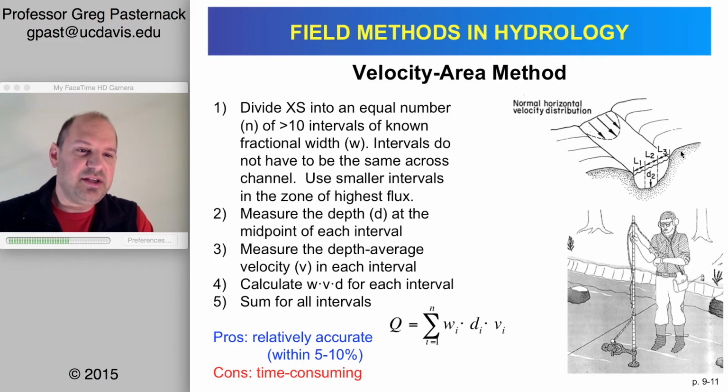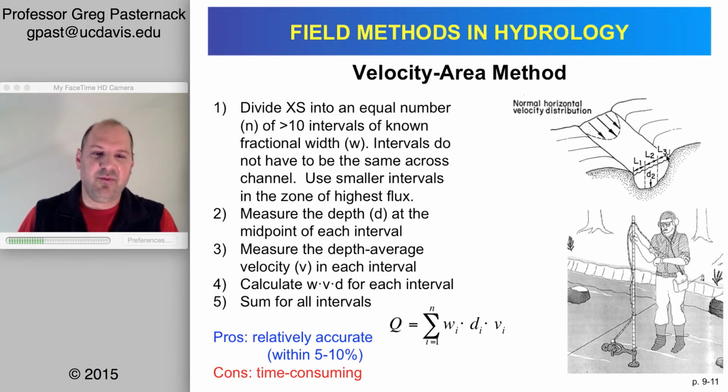The last thing I want to tell you is that for the left and right bank, we're usually not going to treat that as a square, because you can see how much of the square is cut off. This is a very small channel. Both L1 and L3 are fairly truncated on the side, whereas L2 is pretty rectangular. If you have 30 measurements, the far left and far right one are probably going to be represented by a triangle, not a rectangle.